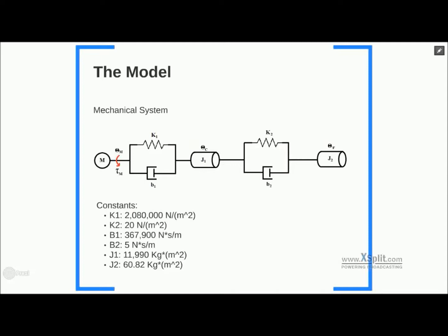The second spring damper system was a little bit harder because first we modeled it as a solid cylinder, but then we decided that we should choose constants just based on how the plot looked to make it model more like a wire. And all those values were calculated based off of actual crane values, right? Correct. We used a real life crane to model these values.